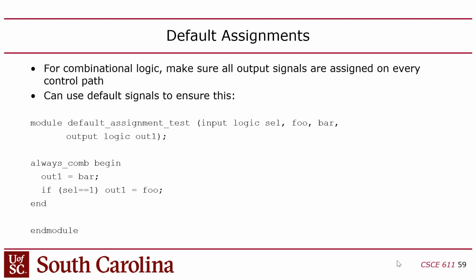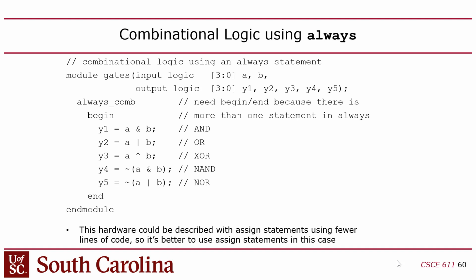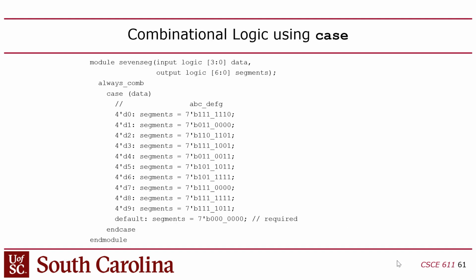Okay. All right, so the last thing I want to mention is this, because this is something you may want to use for lab 1. Actually, scratch that. This is just setting multiple outputs in always comb. That's not exciting. This is what I'm going to show. The case statement. So there is a case statement, which is in other words a switch statement, right? In Java and C, it's called a switch statement. In Verilog, it's called a case statement. But basically, it allows you to put an if then else.